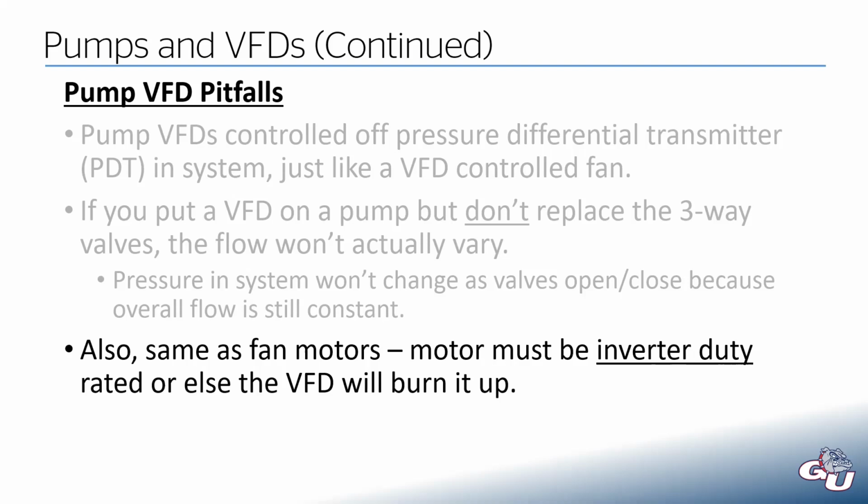It's got to be inverter duty rated. So normally, we don't put VFDs on existing pumps. You could do that as long as you replace the motor, but what we do more often is we just replace the whole pump and motor assembly and then put a VFD on that.